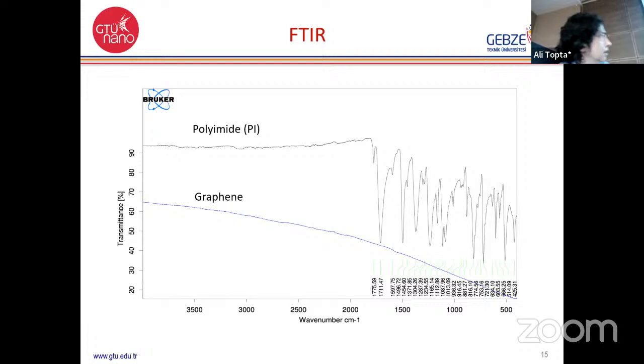We also checked FTIR. So this was nice, okay? So when we looked at the FTIR of polyamide, you see, because of all those functional groups, you have a ridiculous amount of peaks. Each indicates different modes for carbon-carbon, carbon-hydrogen, carbon-oxygen, carbon-nitrogen bonds, which I'm not going to get into, because what we are interested in is that most of the functional groups are gone. This is what we were looking for. So that was quite a nice measurement that we like.